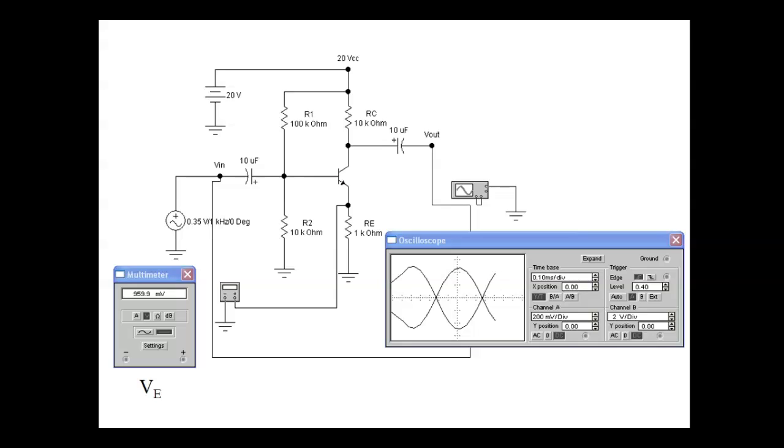We're trying to teach you, okay, if I come up here and I measure my base voltage, and it's not what it's supposed to be, what could cause that? If I knew I had 20 volts right there and I measured 0 volts right there, what could be the problem?